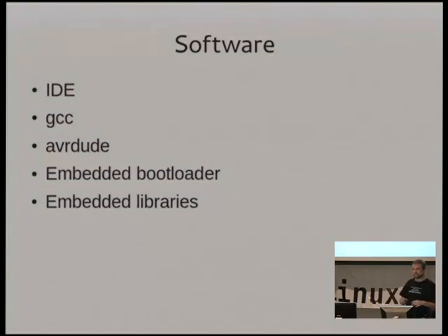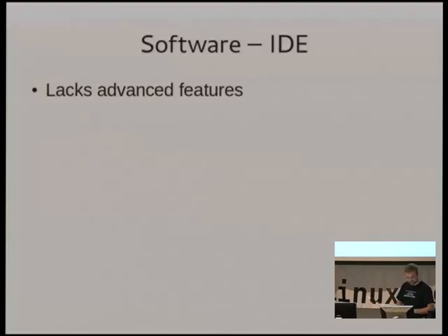During the compilation phase, it'll use the embedded libraries that get shipped with the Arduino IDE to help compile your program as includes. And it'll use the bootloader that's on your Arduino chip normally to then transmit the new firmware and append it after the bootloader.